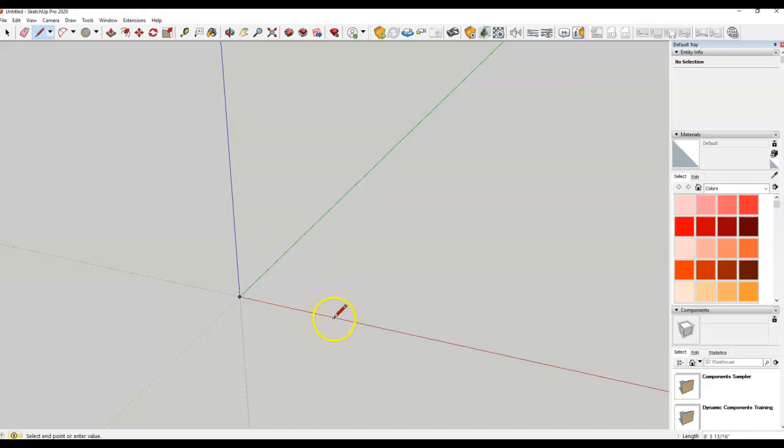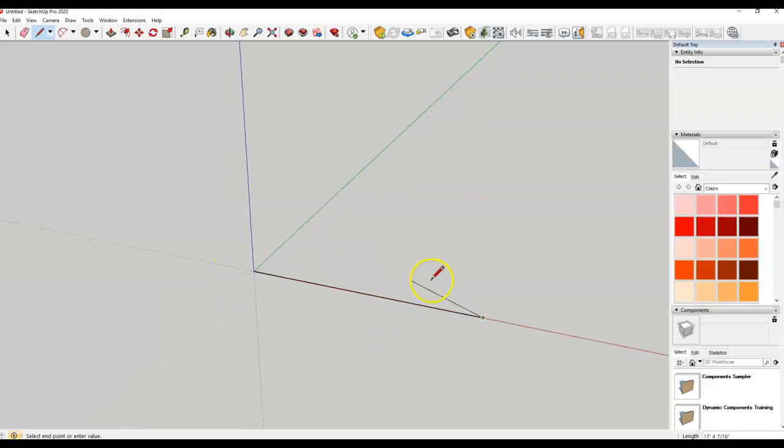So I again do have the advantage of having drawn this house already. I'm going to start by going along the red 45 feet long and drawing over here and then up the green, moving my mouse so I get the green line. That is 90 degrees. It just doesn't quite look that way because this is perspective. You'll get used to it. I do prefer working in perspective. So we're going to come up 25 feet, which is a reasonable size for a house.